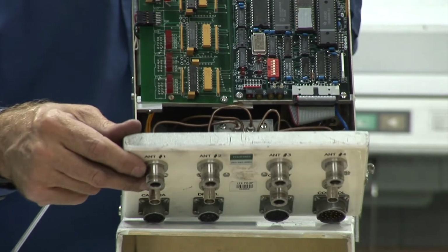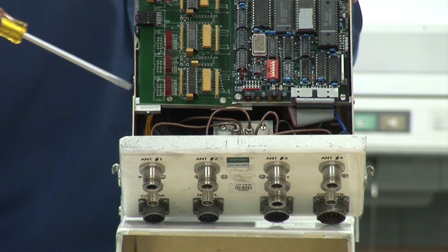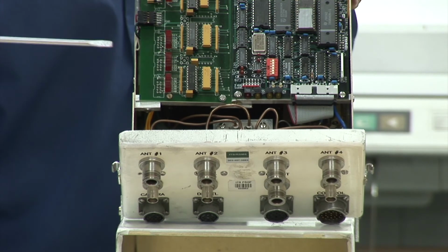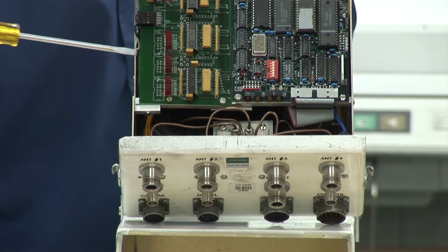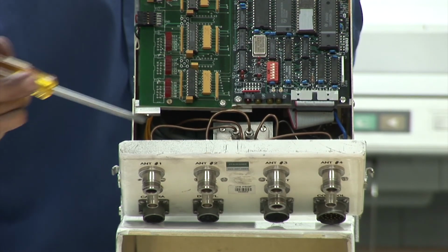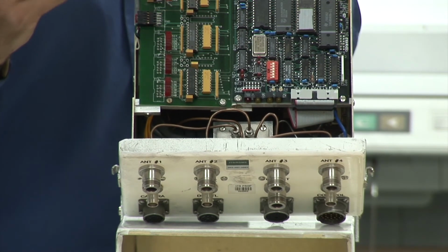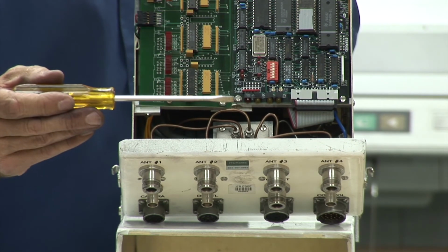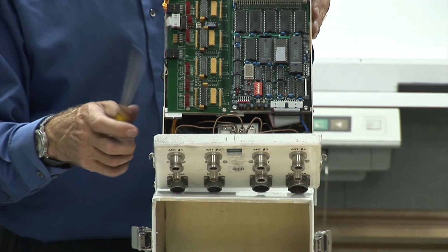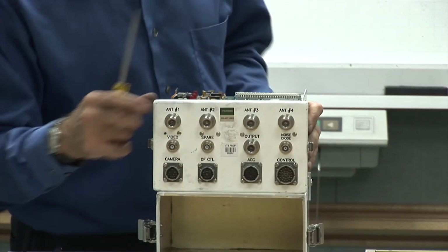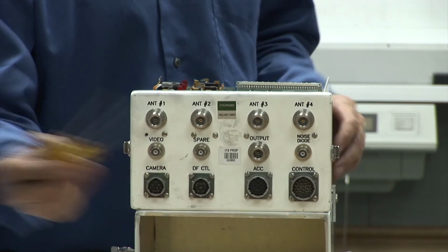So all we do here is take a set of these discrete components, noise diode, RF attenuator, which is also out of view under the circuit board, and YIG filter, some fixed bandpass filters, and actually a set of low noise amplifiers so that we can optimize for a given frequency range measurement configuration, all inside the box, with the relay positions inside the box controlled via the circuit card so that we can command the relays to get the right measurement path through the box, and with the voltage input for the YIG along with the other control voltages coming in on this logic port right here.